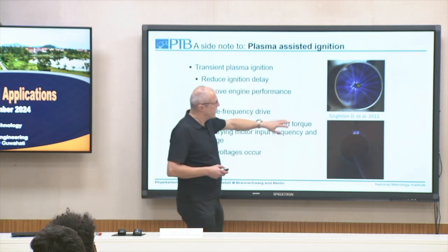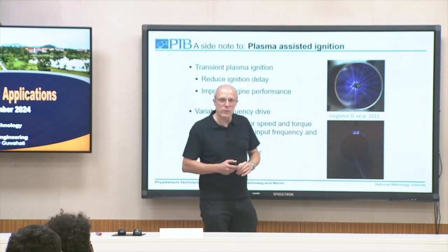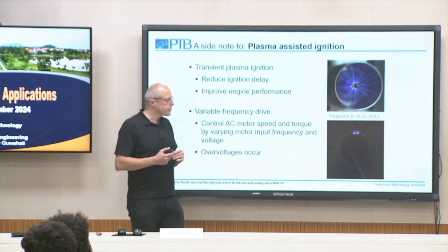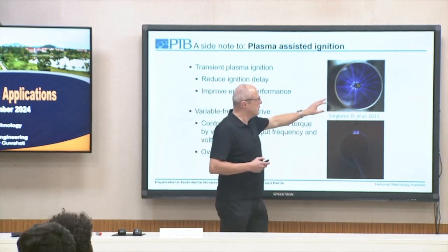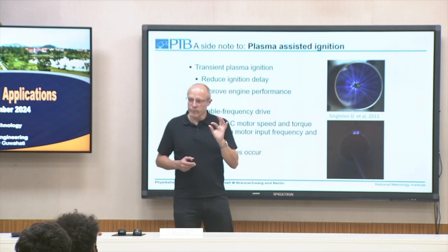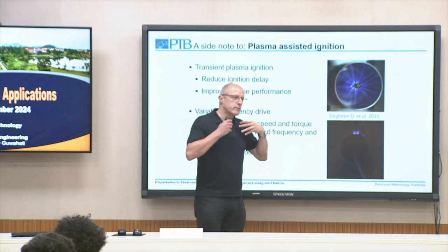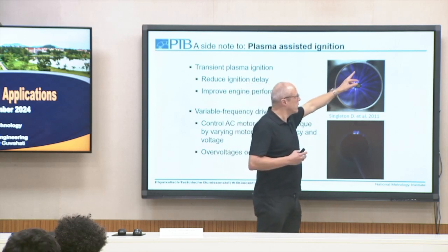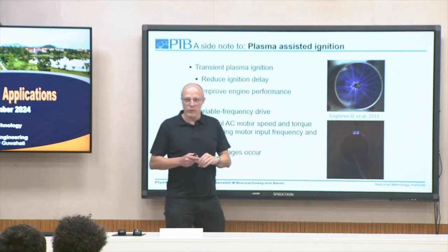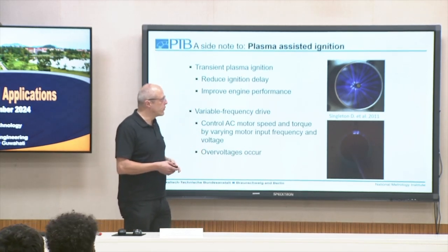You see here the large volume where your plasma occurs. So the idea was not to have only a small volume where we start the ignition using a spark plug, but inside our combustion chamber we ignite the system in a larger volume. So we get rid of the negative effects of our turbulent flow.